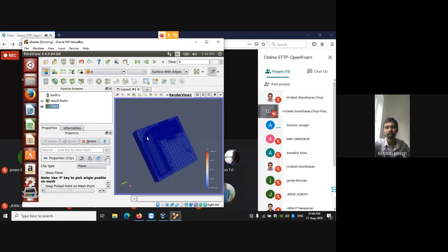We don't want any software like AutoCAD or SolidWorks for creating the geometries in that particular case. We can even model a pipe using block mesh, but it's quite difficult. We need to give all the vertices, and they should be arranged in some sort of manner, and everything is quite difficult.